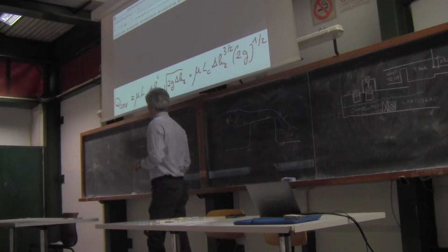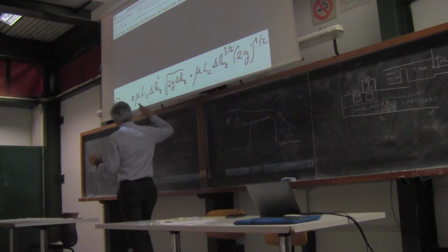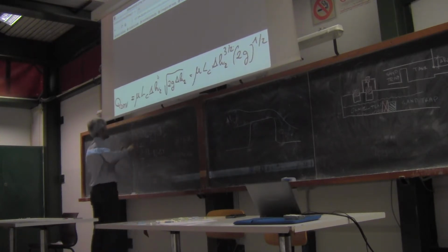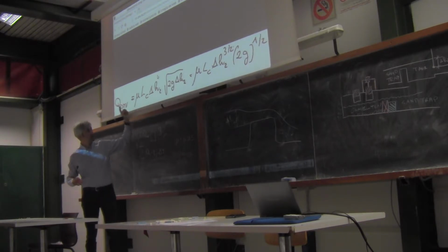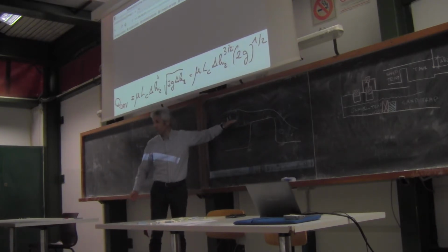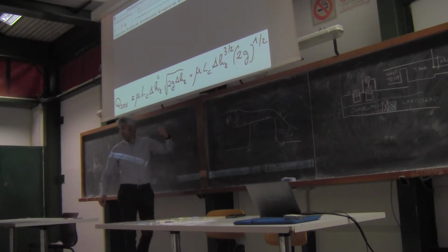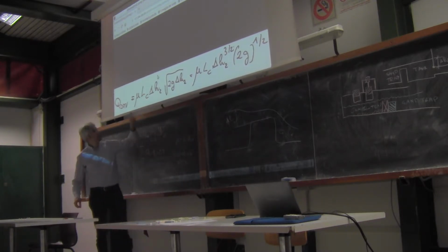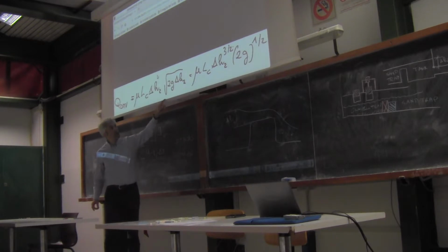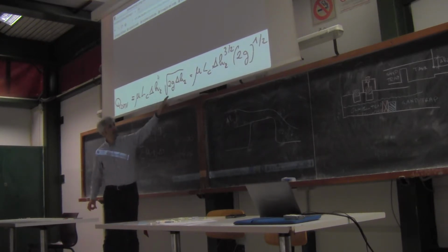Okay, so again, this relationship says that the environmental flow is given by the product of μ, Lc, the width of the weir, delta H2, the water elevation over the weir measured with respect to the crest of the weir and the upstream water level, multiplied by 2g, gravity, again delta H2.